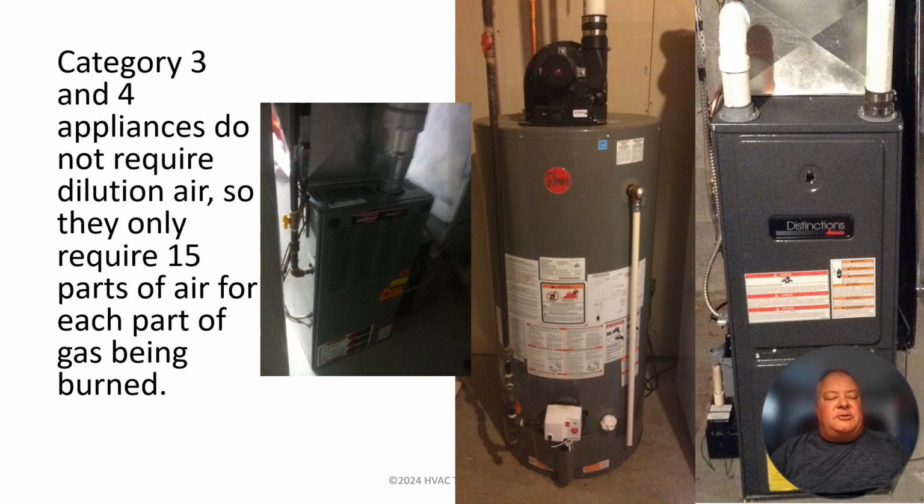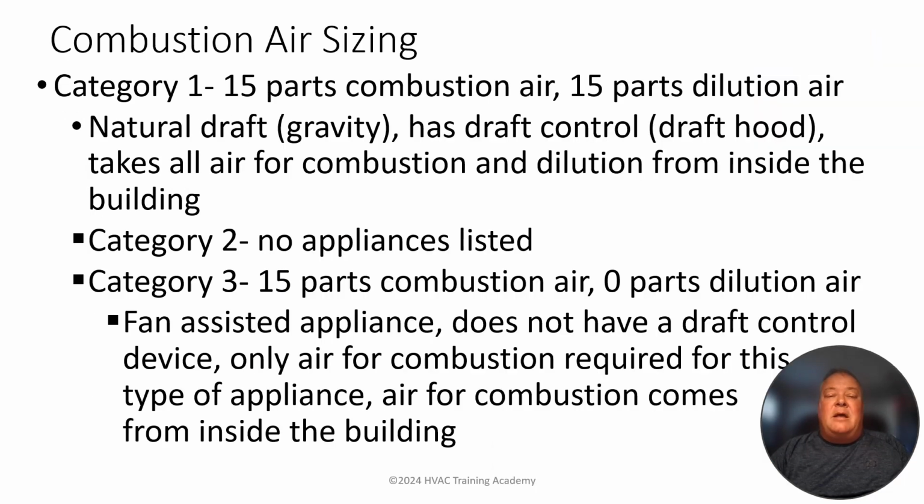So the natural draft needed 30 cubic feet. These examples will need 15 cubic feet. And again, just to reiterate what we've got here, category 1 will require 15 parts of air for combustion, 15 parts of air for dilution.